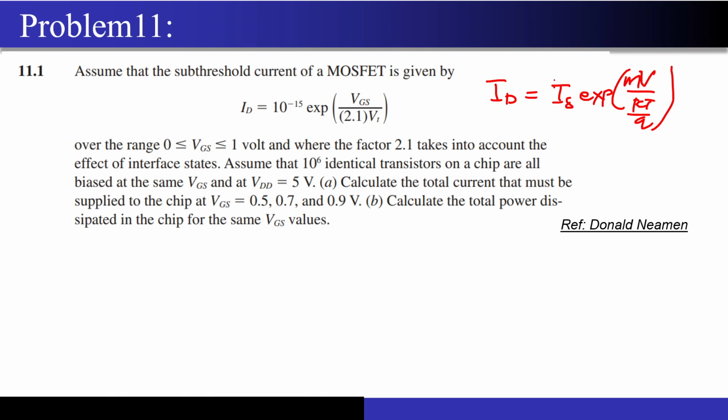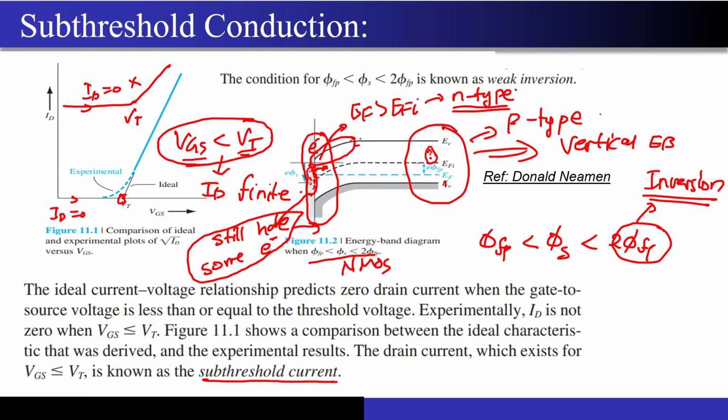Because you can see from this energy band diagram over here, you must have seen the minority carrier concentration in the PN junction. Let's say this is your background minority carrier concentration, and this is at the depletion region edge. Now this carrier concentration was proportional to e to the power qVA by kT. I hope you remember this.